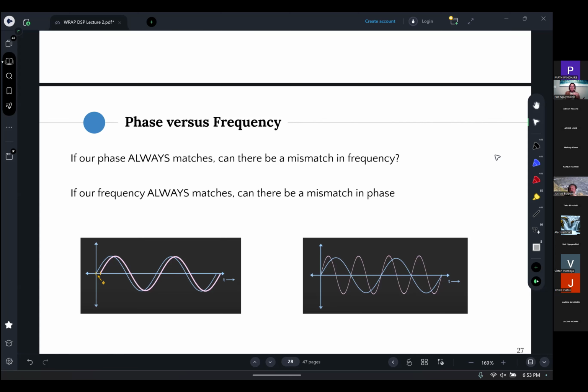So the received signal had some sort of offset, and then we just matched the offset during demodulation. So if we can do that for any sort of phase offset, then we're automatically correcting for a frequency offset as long as we can always keep that phase aligned.